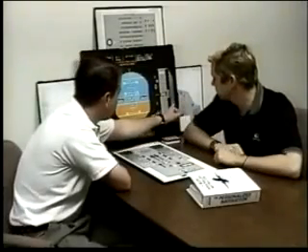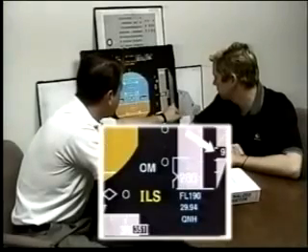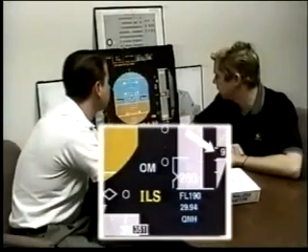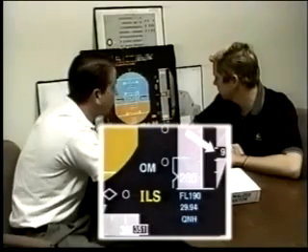Over to our IVSI. When do you start getting a numerical value? Anytime it's greater than 200 feet per minute. Okay, would the pointer and the numerical value ever go amber? Yes, anytime you have an excessive vertical speed.